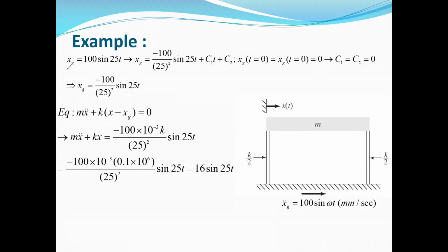So we have the acceleration, which is 100 sine 25t, and also we can find the displacement of the base by integrating the acceleration two times.